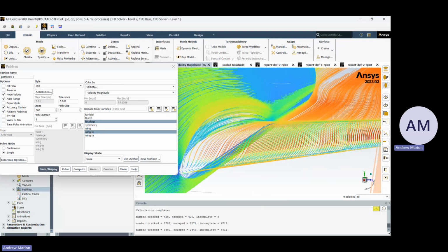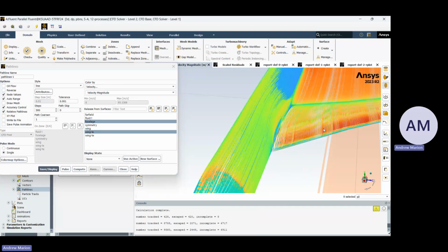Ways to minimize this are like making a fillet from the wing to the fuselage to smooth out the transition between. There's other ways. There's wing fences, which they use in between wing planforms, and that's a way to keep the flow straight. Some wings will have different sections, one curved at this angle, one at that angle, and the flows from those different sections can interact with each other. So they have a fence run along the wing to prevent the flows from interacting, and that minimizes interference drag.